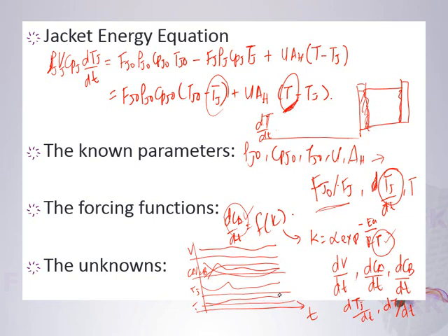You have another checking parameter. Do you know your tau? Your residence time? Okay, your tau is V over F, right? So your tau is actually your T in here, because your tau here actually represents how long the fluid will be in the reactor. So once you have got your F, your V and so on, then you check by using this equation. So is it okay by that volume? You use that flow rate. Can the volume cater for that? Your tau is actually your T.